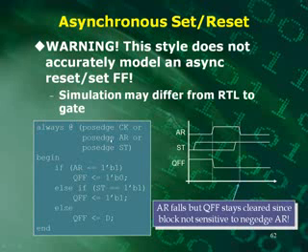Yeah, here's the problem. Okay, we come along. Let's start over. I'll do this again. Let's say our Q flip-flop is high, and we come along, and on the positive edge of the asynchronous reset we want to clear the Q flip-flop. And we do that because we have a pos edge of AR.